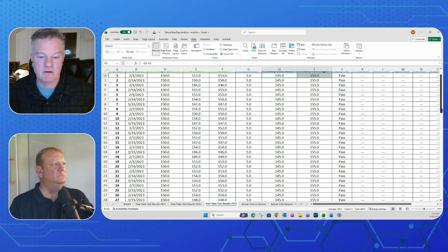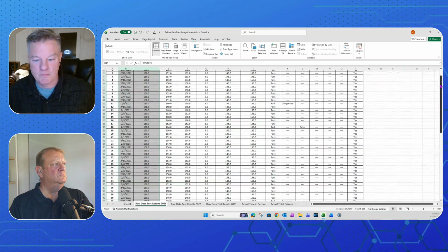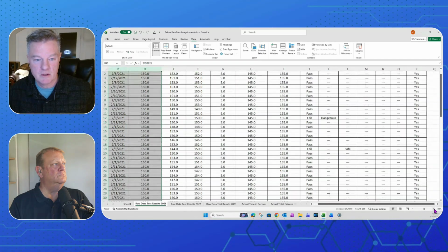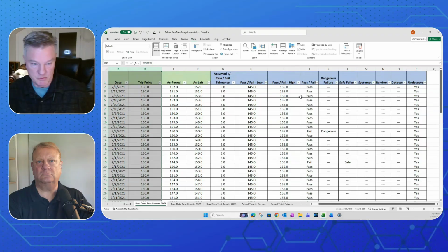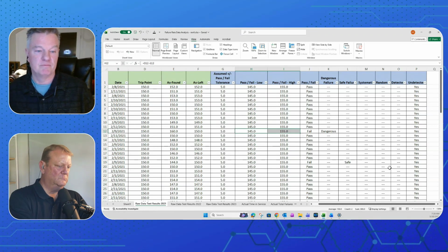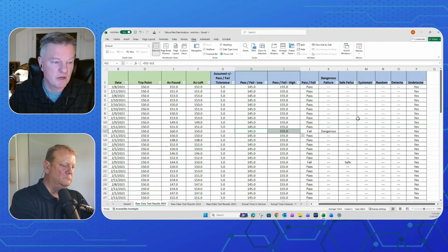And I'll see if I've got a failure hiding in here. Let's go to year one. I think I got a failure early. That tolerance was set up by looking at other protection layers, alarms, and everything else, to make sure this was big enough that we limited it. It's not the 0.1% accuracy, because that's what we bought. So we had this big 10 degree or 10 PSIG window.